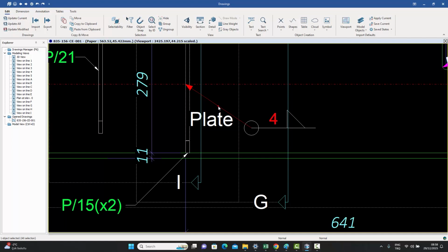And once it's selected, you can move it around like this and take it to another point. And once that is done, each leg now has a middle point. So if you select it again, you can select this particular point and break that into multiple legs as well. So you can basically break the welding symbol into multiple legs from that point onwards.